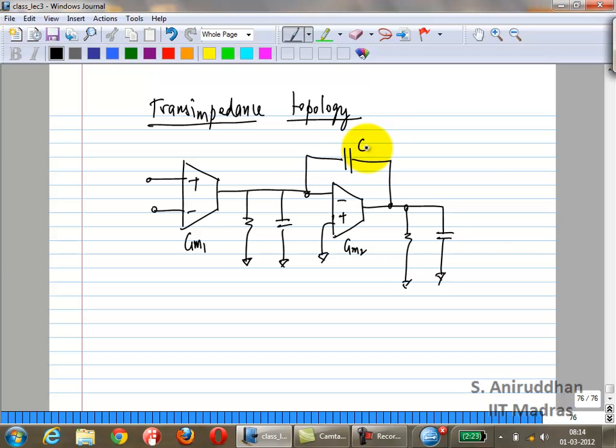We looked at that also. If you add a buffer, the most commonly used buffer is the source follower. We looked at the source follower. The common mode range is limited, quite a lot. If you put in some general numbers for VT and VDD in some of these submicron processes, the swing will come out to be maybe 0.3 volts, which is totally unacceptable, 1/3 of your supply. What you are normally used to is supply minus VDsat on the upper side, and VDsat on the lower side.